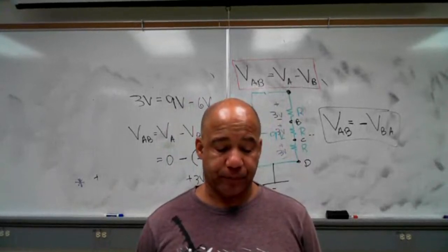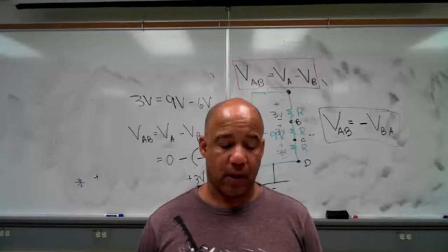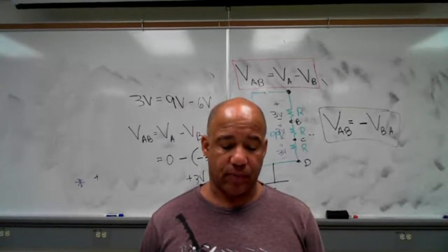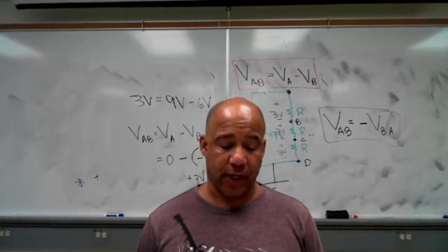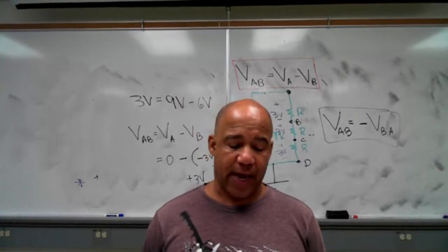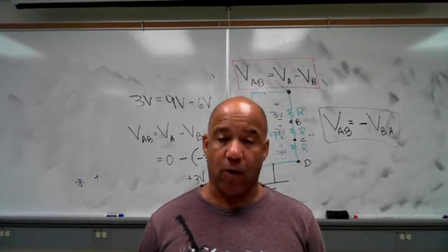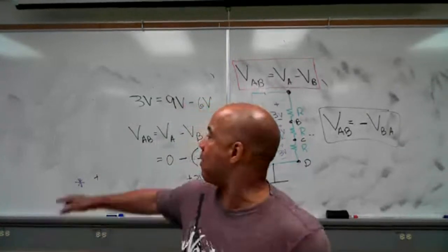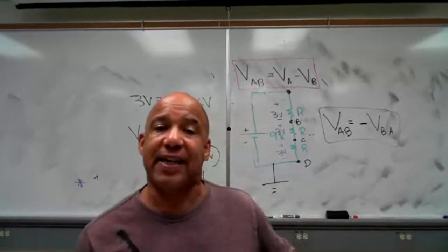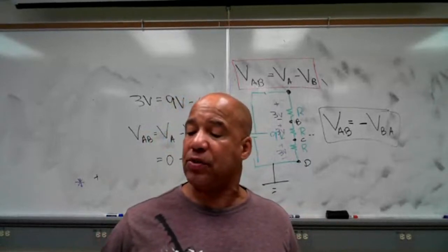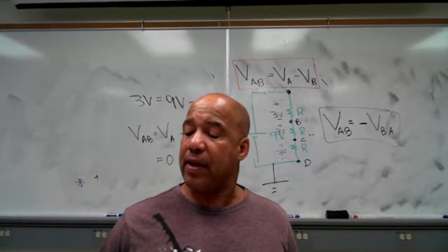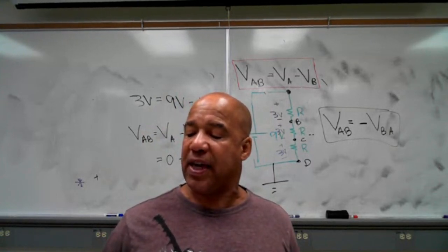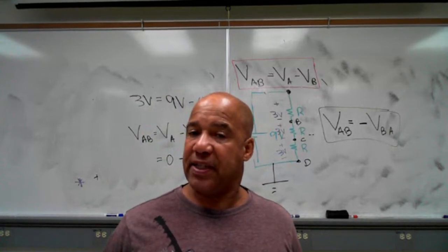Look at figure 4.1. What is he doing in figure 4.1? Well, in figure 4.1, he has a 12-volt battery. He has two resistors, R1 and R2. And if you look at it, he's showing you that in figure 4.1A, notice where he has that ground symbol. Again, it's not grounded there. It's not earth ground. That's reference ground. So all that's saying is take your black lead and put it between those two resistors at point B. If you do that, and notice over to the right of the circuit, he has VA, VB, and VC.